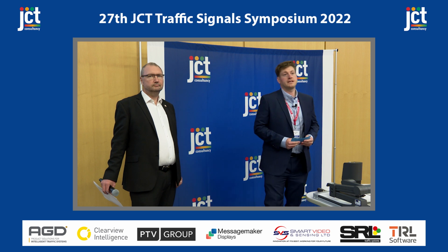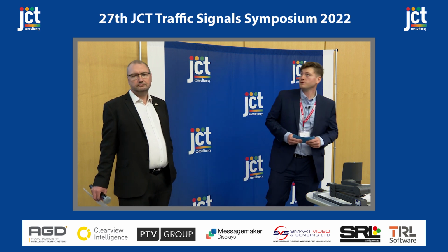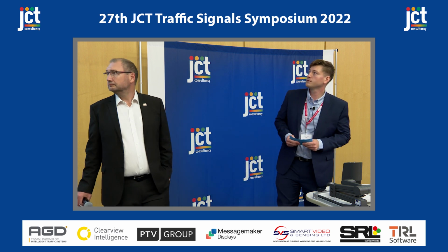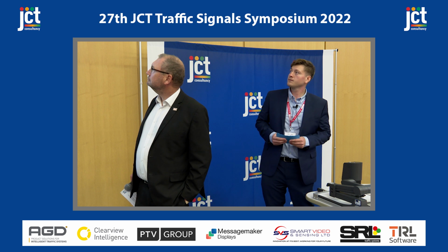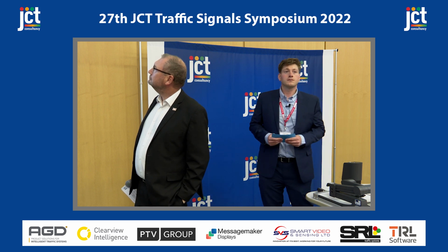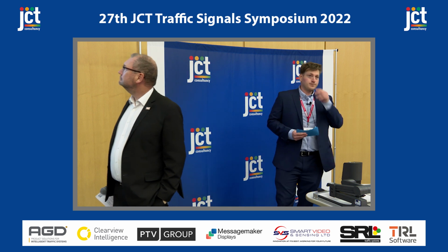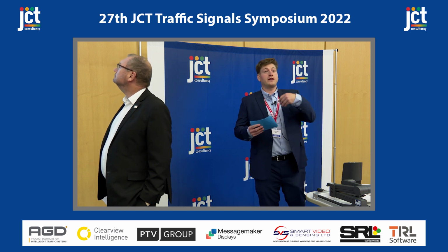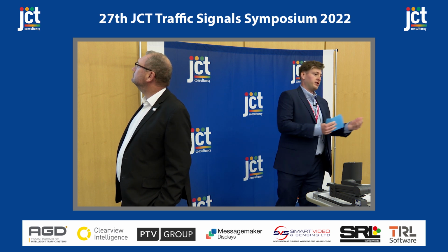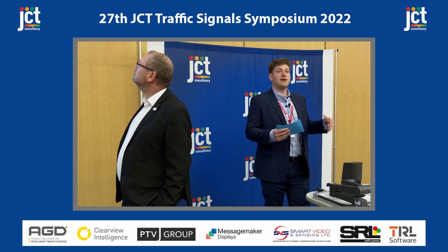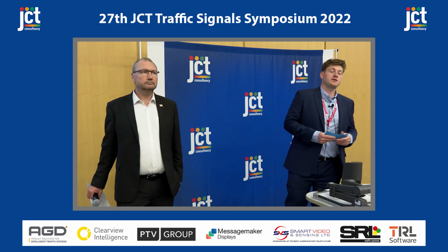Yeah, but I can take that risk. I can also see that if you turn right from the east here and go north, as you see in the picture, once you've made that manoeuvre on the road, you're stuck on the road. You can't get back onto the cycle track because of the curbs there. Yeah, so for those that want to make that manoeuvre within the junction and then get back into the cycle lane, in a lot of the designs we do, just after the junction we have gaps within the segregation, so cyclists can merge back into the cycle track if they wish to do so.